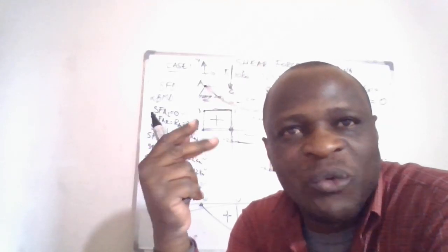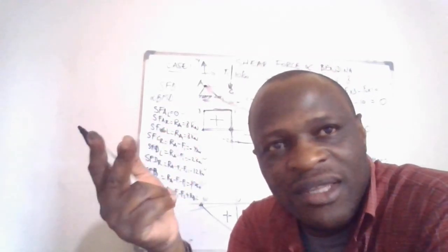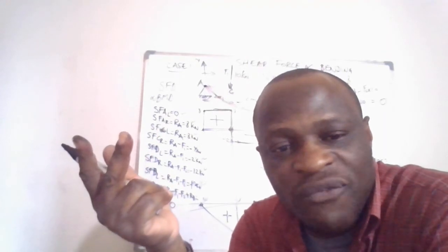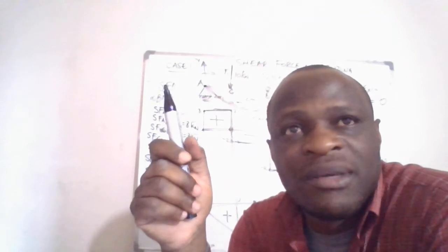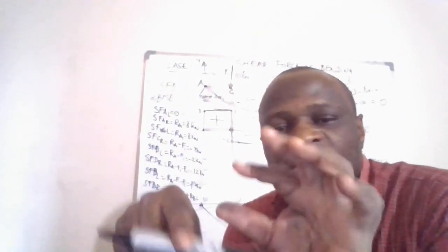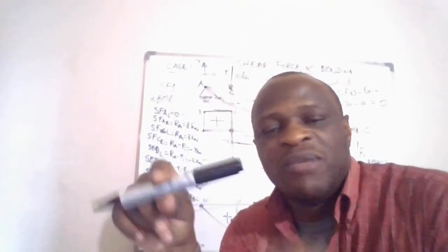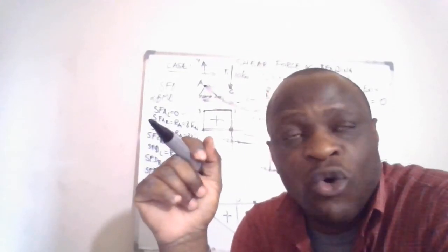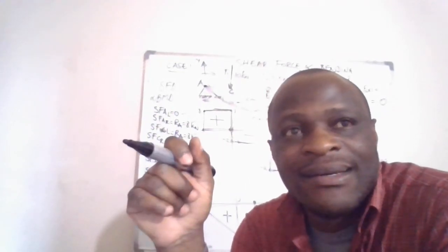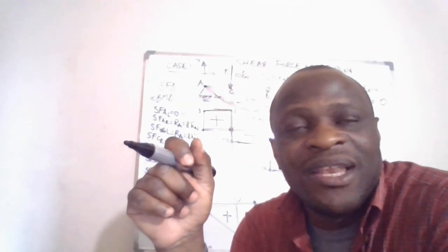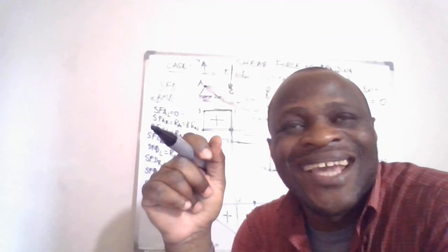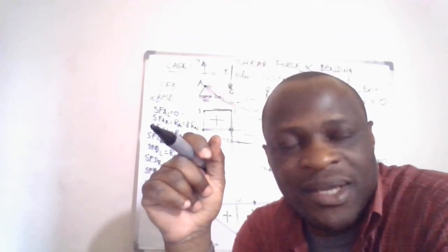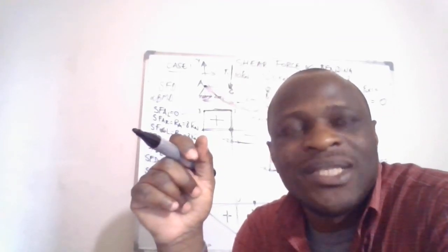The failure will take place either by shearing off the beam, which takes place at the cross section, by cutting off the beam and trying to slide the spans of the beam one over the other, or else by bending the beam, and the beam will take a deflection, and if that deflection is excessive, the failure can take place.